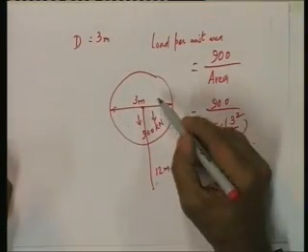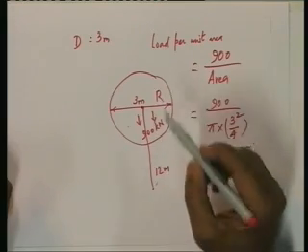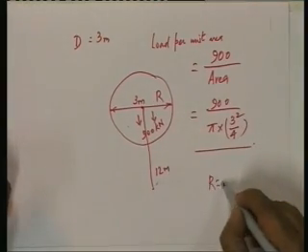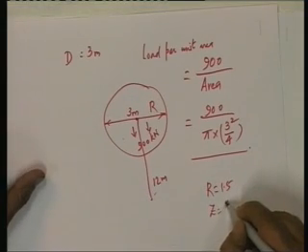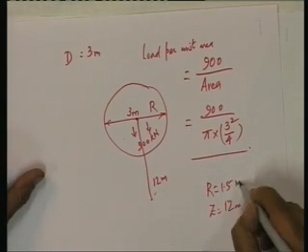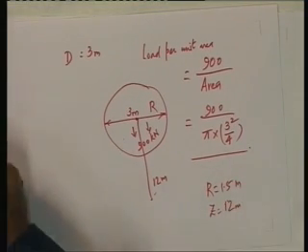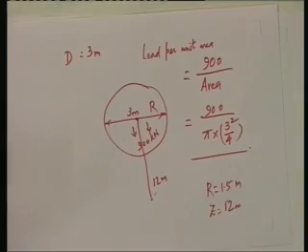The radius R is 1.5 meters, the depth Z is 12 meters. So, we need to now use the influence coefficients chart or the formula depending upon whether this value of the ratio R by Z lies within the range of the table or not.